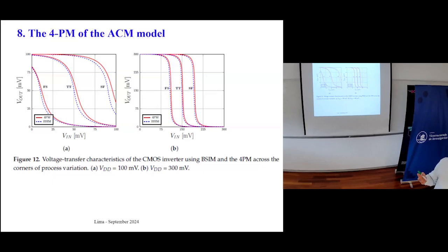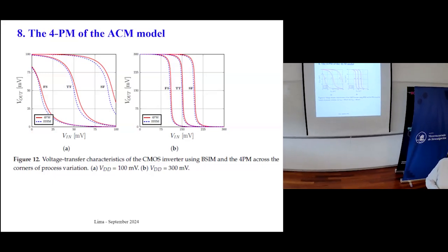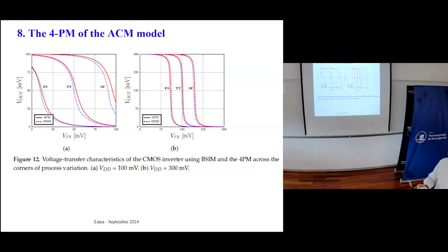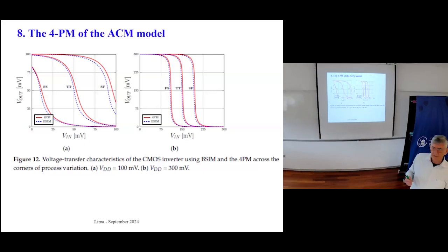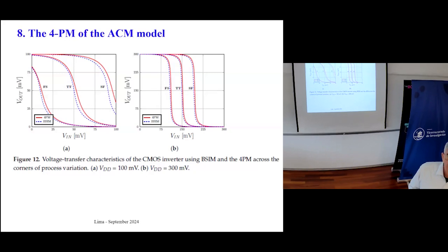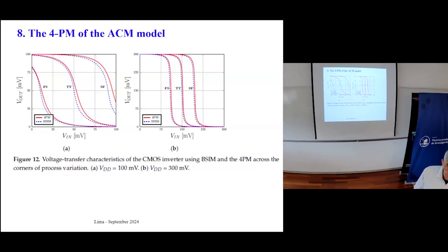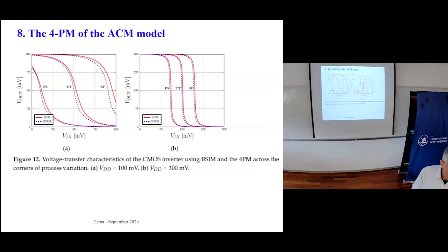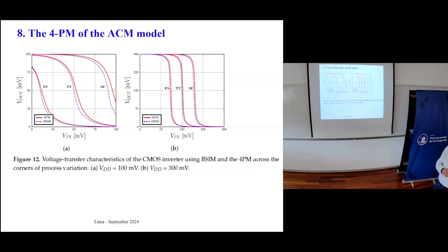Typical off-the-shelf inductors have a Q around 100 to 150, but inductors in integrated technology have a Q maximum around 8 or 10. This is too poor. They are really lossy and waste a lot of energy, so it's difficult to have an oscillator using low Q inductors.